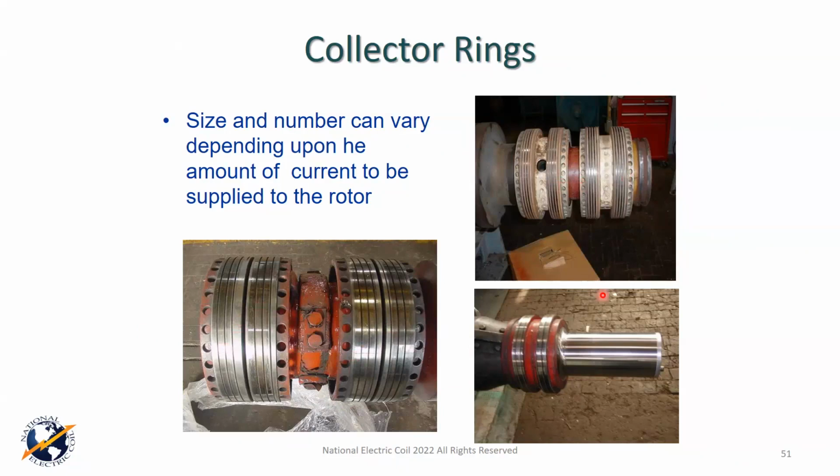These carry more current. In smaller units, you can find these where they're solid, but traditionally, most of these have a spiral groove inside of these. That spiral groove helps to maintain proper commutation and handle any kind of dust you get from your brushes. Some people also call them dust grooves. The dust goes into those and allows it to blow out through that and not interfere with the commutation. It's important to have the right brush grade because the carbon itself puts a little bit of a glaze on these surfaces so that it properly slides mechanically and allows for proper commutation electrically, okay?